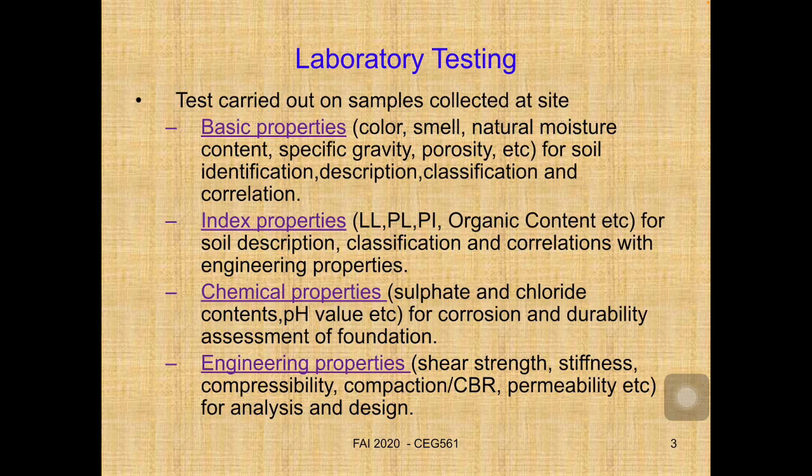That is an example. This classification of soil is important when you want to design later. Because if you classify your soil correctly, that would be the assumption for the soil characteristics when you want to design any construction, or when you want to calculate the bearing capacity based on the soil classification, because the characteristics of cohesive soil and cohesionless soil are different.